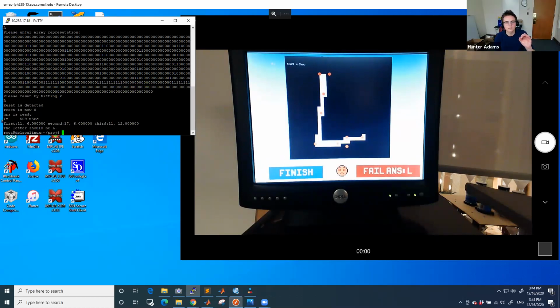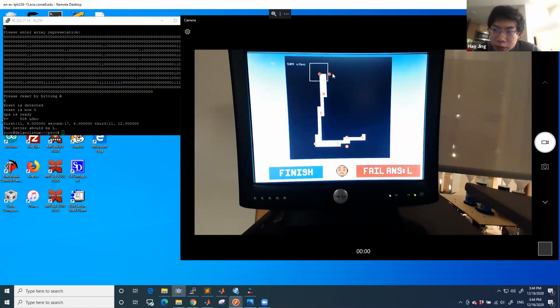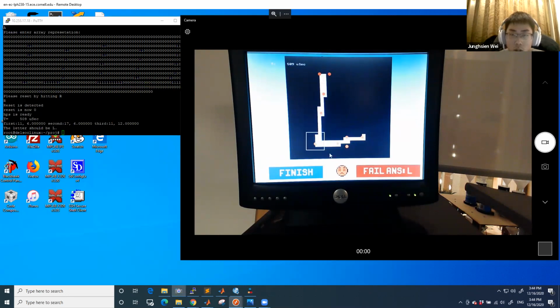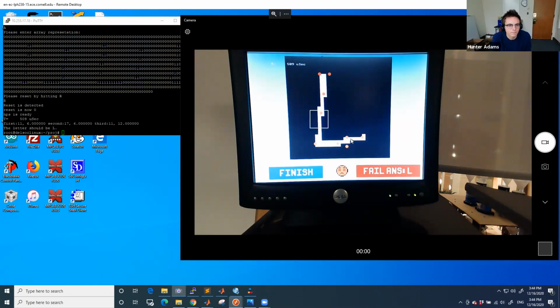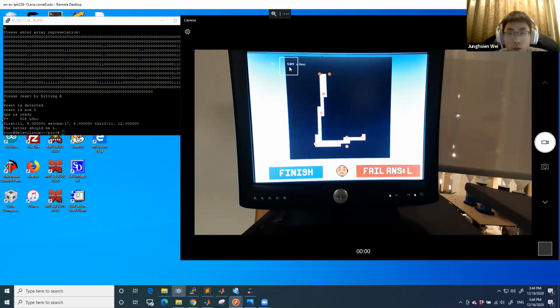Are the red dots there showing the output of the corner? Yes, the corners from the FPGA output after non-maximum suppression. The result we got has more corners than these dots, but we do the non-max suppression, so it gives us the highest value from each 3x3 matrix. And our computation time for the Harris Corner algorithm is about 0.5 milliseconds.